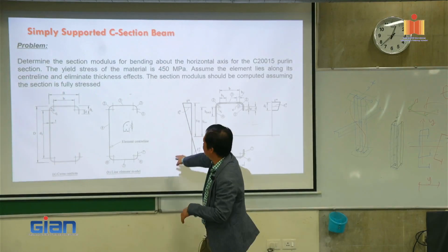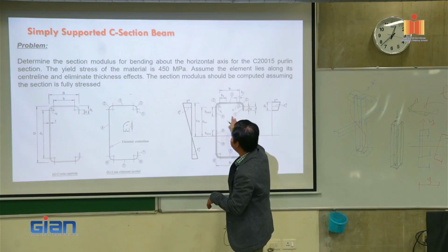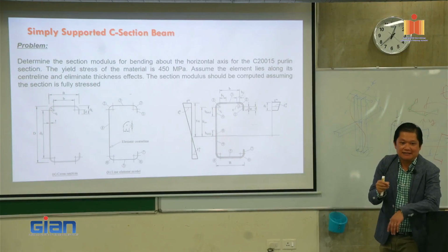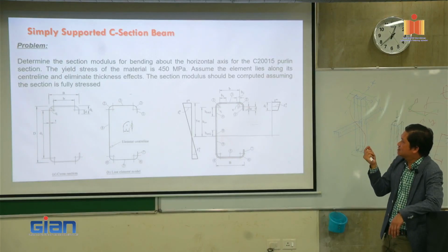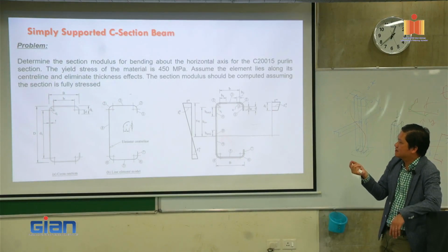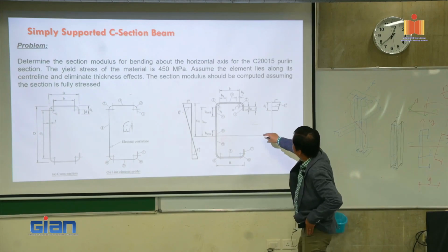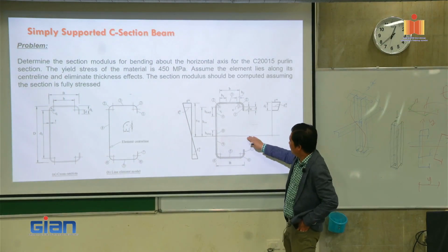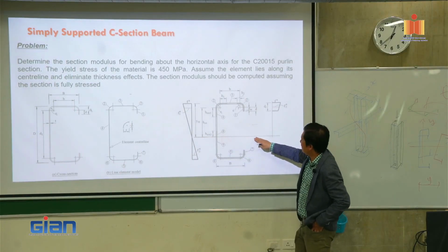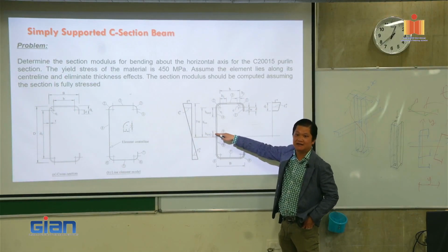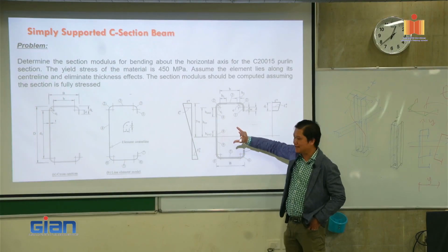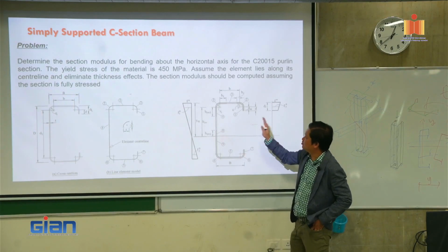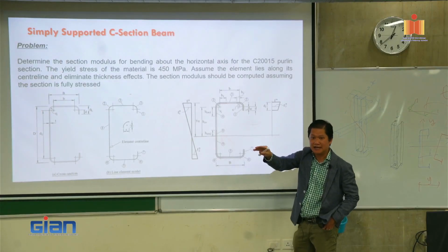Okay. Now I will work it through for you step by step to calculate the effective width, sorry, the section modulus for the effective width section. Okay. Now, as I mentioned before, this is the beam. So we have the neutral axis lying somewhere below the symmetric axis, and you can see we need to break it down into different elements.